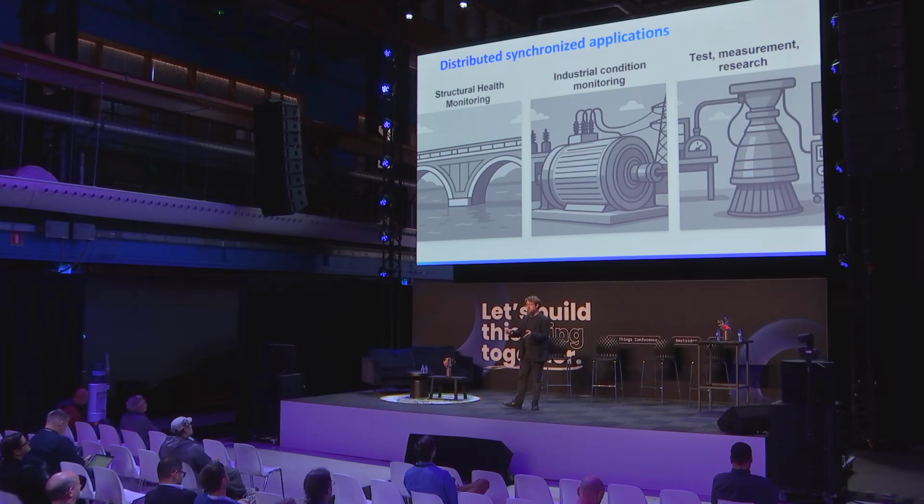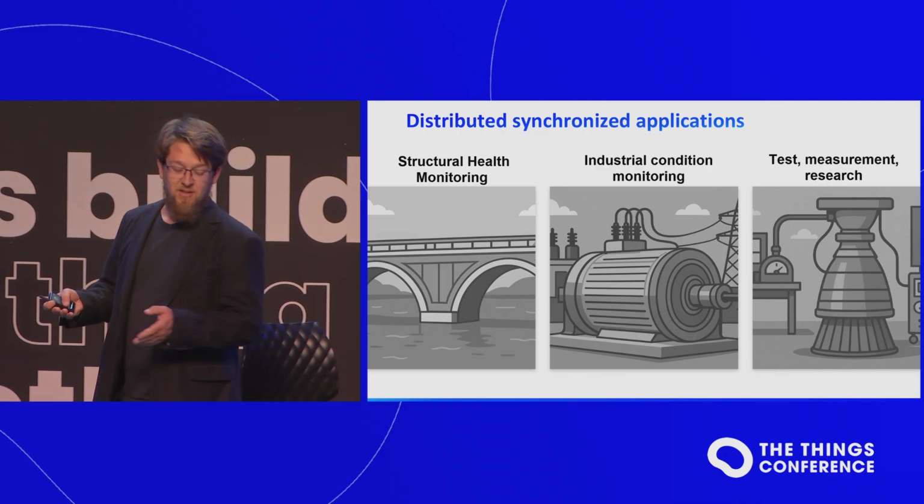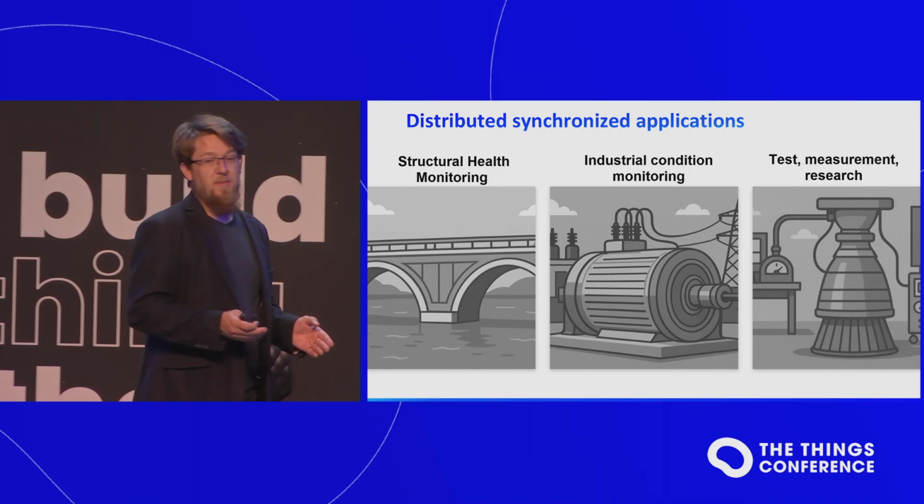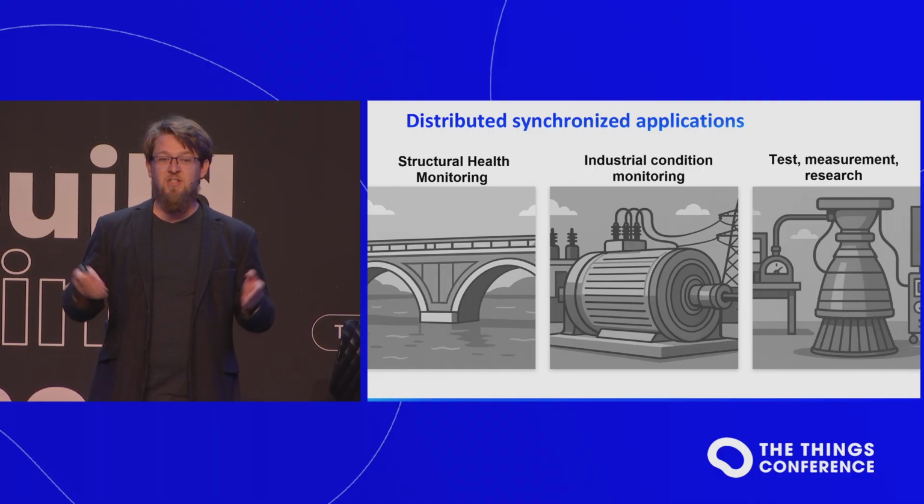So we can do structural health monitoring. The simple way to think of this is we don't want the bridge to collapse in a basic sense. So what does that mean? We want to see if it's standing upright. We want to give it an impulse. So, me jumping on the stage, you would see the waves across the stage rippling through the structure. The same happens on the bridge, except you maybe have a truck or an impact tool hammer, which gives you an impulse response of the bridge, and then it will respond to the mechanical perturbation. So we can tell if this bridge is standing, and we can see over time what happens with it.